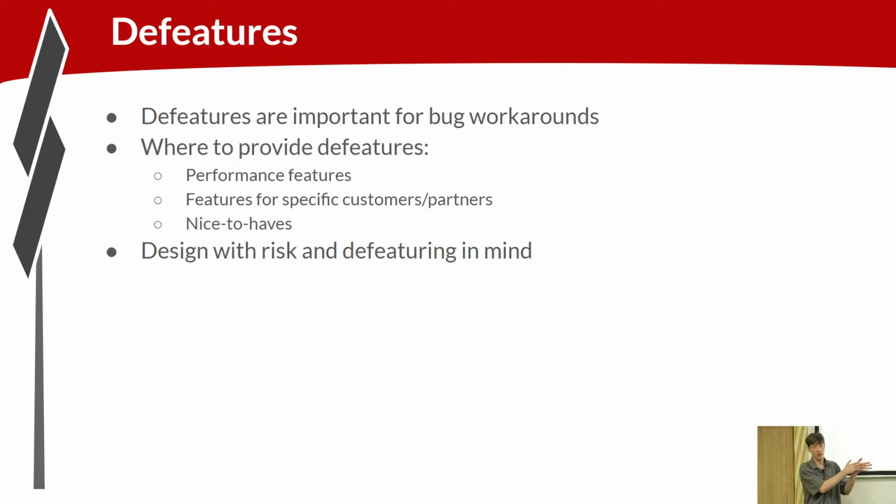Originally we designed our core so that it would issue an instruction every 3 cycles. Then we sped that up so we could issue an instruction every cycle. We might want a D-feature in our core that reverts us to that every 3rd cycle behavior. So we might keep that valid logic, the 3-cycle cadence, with a configuration controlled by a control status register that says I want to revert to the every 3rd cycle valid behavior. If we have a bug post-silicon, that's probably too much of a performance impact to ship to a customer, but at least we can de-feature so that our core is functioning correctly.